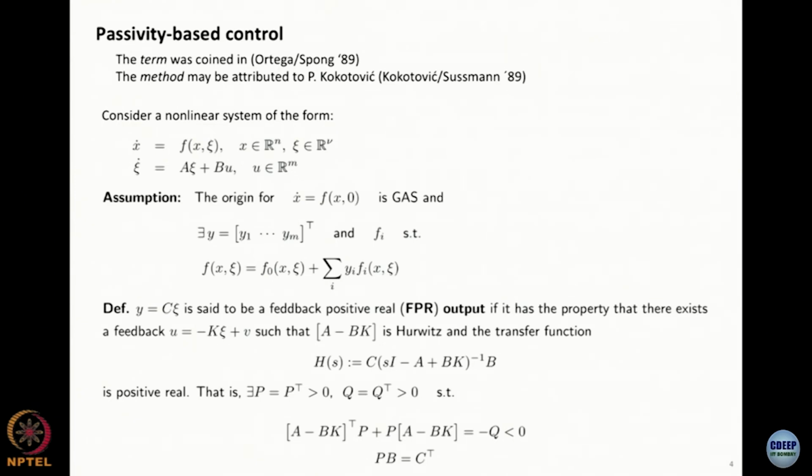So here, after applying the preliminary feedback and transformation and so on, let's suppose you end up with this system. You already applied the preliminary feedback, but you say, okay, I'm going to add another feedback to complete the stabilization task because I didn't manage to linearize this part. This is what people know in feedback linearization as zero dynamics, with respect to the output psi.